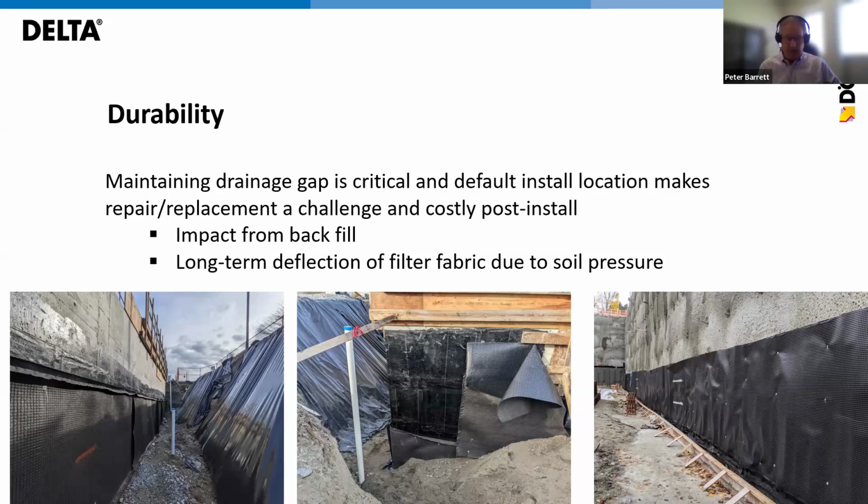Membranes and products exterior of the membranes should not absorb water or have their function damaged by water. The material behind the membranes benefits from durability, which is a good reason for a concrete foundation wall rather than, say, wood or other alternatives. Additionally, selecting a quality of material that will maintain flow rate performance, both in the initial backfill and with the sustained force over time, during the entire service life is essential, even with a concrete foundation.